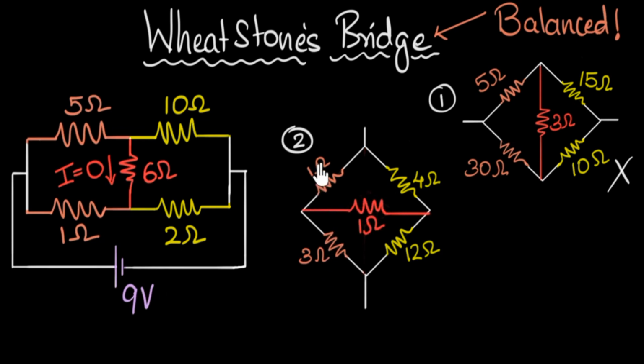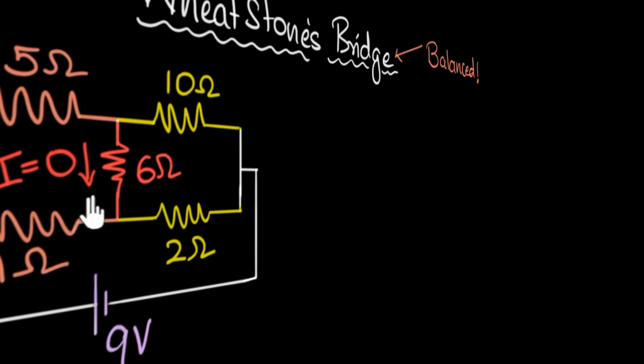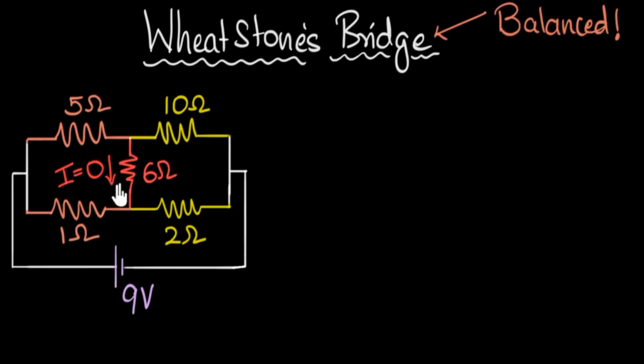You know, these are in series, these are in series, and the 3 are in parallel. So don't get confused. Definitely the resistor current here won't be 0 because it's not a Wheatstone's bridge. On the other hand, if this resistor was connected here, then it would have been a Wheatstone's bridge. And now we can check the ratios, 1:3, 1:3. Now the current over here would be 0.